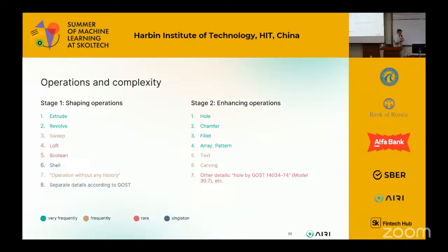What does it mean? It means that when we take the point cloud, the images of some element, we want to provide a number of operations in the CAD software sequentially, which gives us the final model. So these operations are usually oriented on some geometrical or physical operations, like extrusion, like revolving, sweeping, shelling, and so on. All these operations in combination may give us some final element, final detail that we want to put in production on the manufacturing stage.